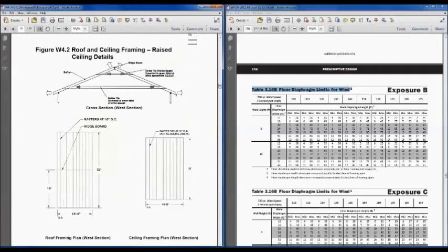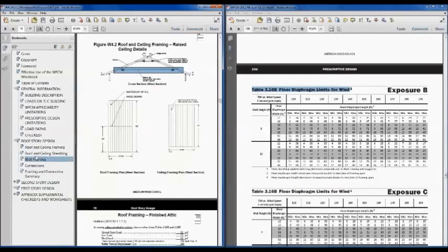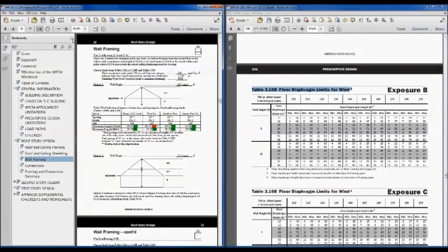So the other thing that's happening in the other direction is if we have this raised ceiling right here, let's say that goes on up into the ceiling, and in that case we may have both a collar tie and a rafter tie. We may be framing the gable end walls up to that point, and let me get down there to that wall framing detail.